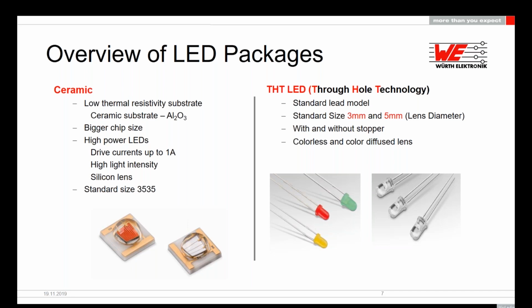The common size on the market is 3.5 by 3.5 millimeters. Very classic but robust is the THT LED, the through-hole technology LED. We offer them with 3 mm and 5 mm, with or without stopper, with a transparent or colored diffused lens.